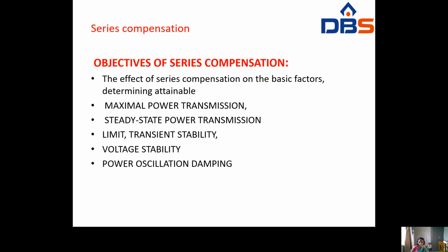So in series compensation, the objectives will be maximal power transmission, steady state power transmission, limit transient stability, voltage stability and power oscillation damping.